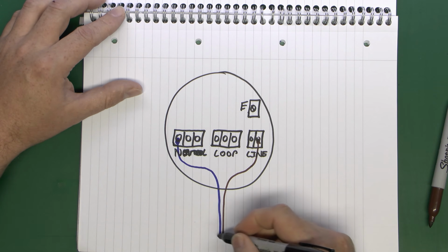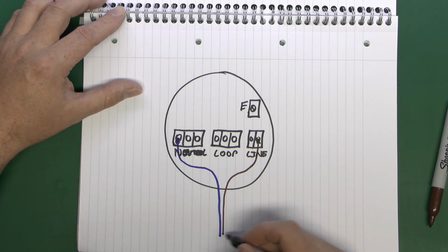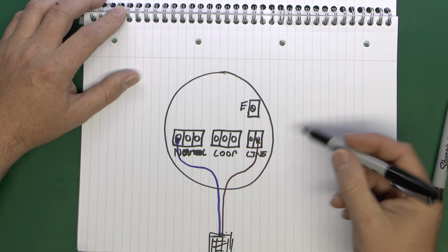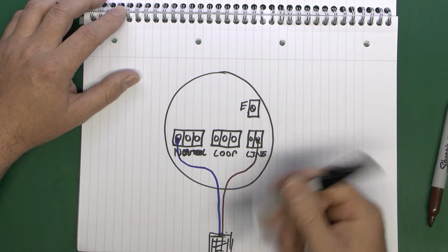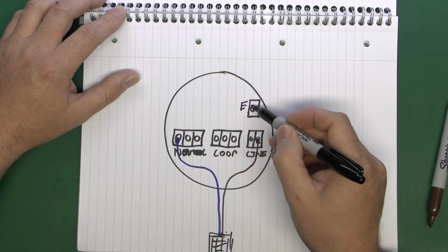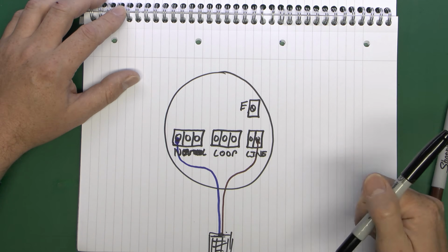So at the bottom here, this is where your light bulb, whatever, will be connected, and that's generally the holder, which just hangs down into the room and lights it up. And these are typically only 2 core. If it was a metal one, then you would simply have an extra earth wire going down to the metal holder.